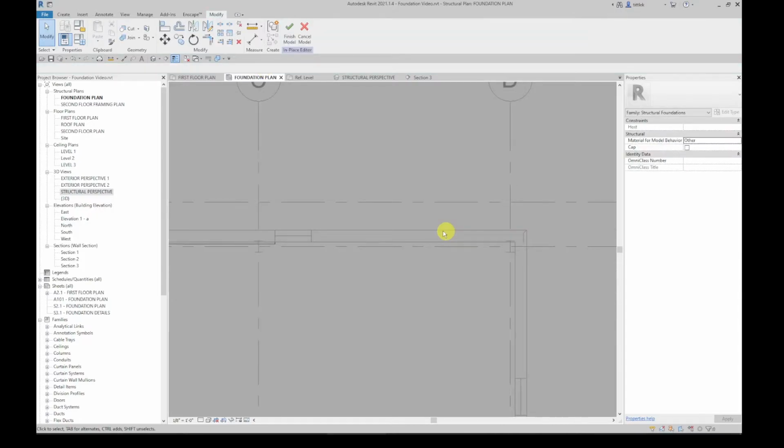All right, so let's go back to the foundation plan. And I'm going to create another sweep. This time I am going to use, in sketch path, the outside face because I don't need to do that anymore to get these sweeps to work. Again, I'm going to go to that opening, hit the green check mark, select a profile. Again, this one's full height wall,